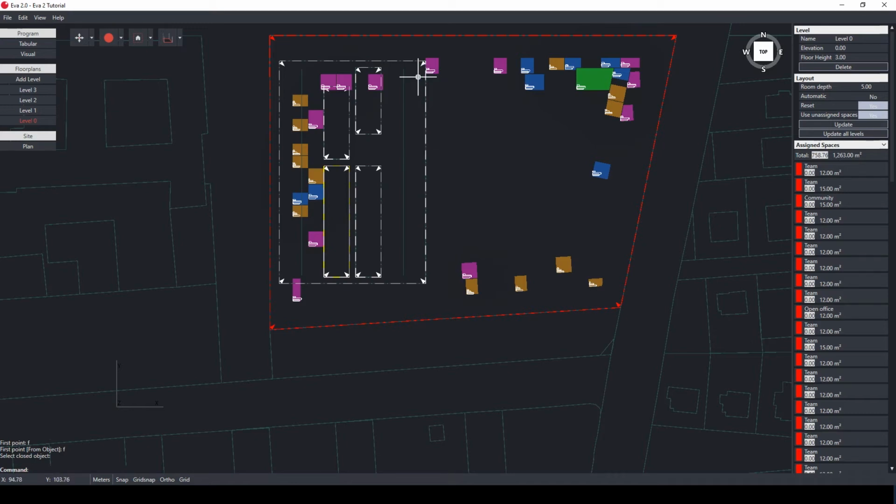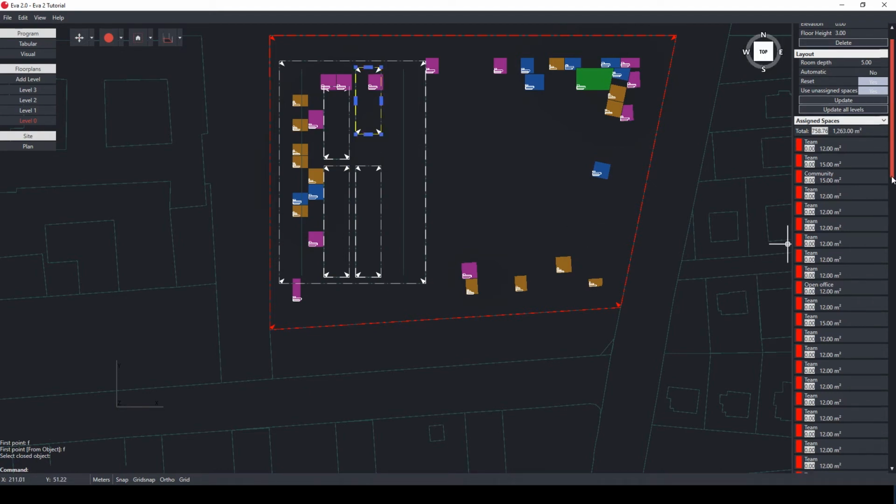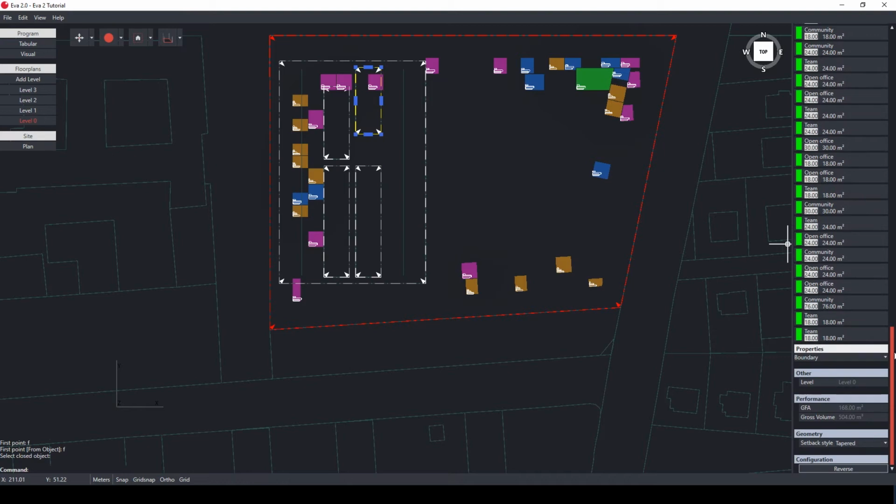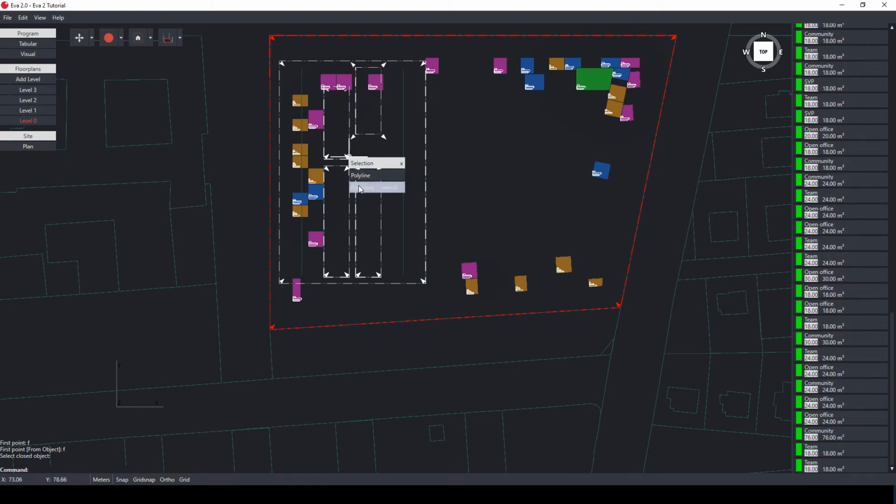To close the boundary line, always go to Command C for close. In our example, the inner courtyard's arrows are still pointing inwards. So this would be an outer outline, a house inside the house, which of course cannot be displayed like this. To change this, I can go to reverse here and change the direction of the arrows. Now I get a building with 4 inner courtyards.